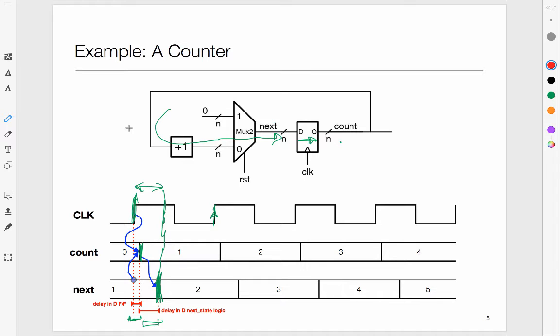In your circuit classes, you might even see things like RC delays. It's a long line, and in fact, in modern circuits, the RC delay, the delay through the wires, dominates the delay through the gates. If you look at the overall delay budget, the work we are doing in a single clock period, most of it is actually devoted towards the signal just traversing. Our chips are big, like the big Intel processors could be 3 centimeters to the side or something like that.